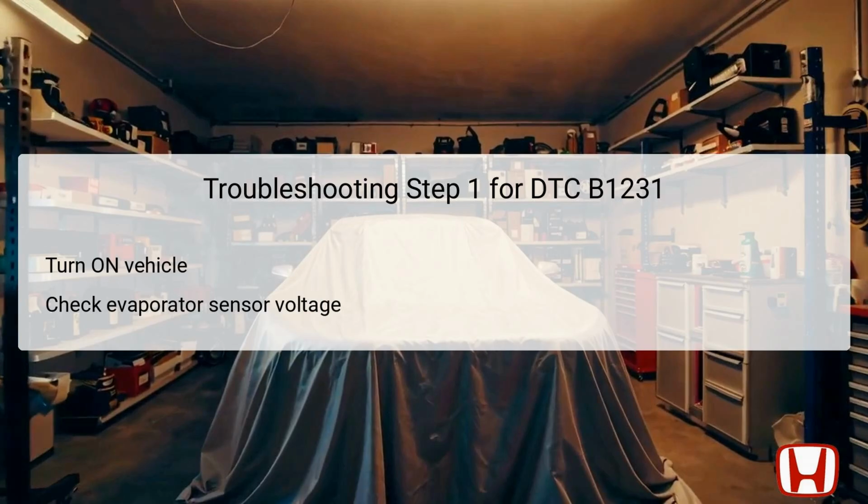issues. The first step in troubleshooting DTC B1231 involves switching the vehicle to the on mode to power the necessary diagnostic equipment. This allows for initial checks of the evaporator temperature sensor's functionality. During this phase, it is crucial to observe the voltage readings coming from the sensor. If the input voltage is unusually high or does not align with specified values, it indicates that there may be an issue present in the sensor circuit that needs addressing.